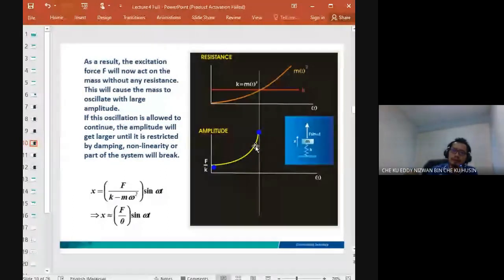When the operating speed is close to the natural frequency, you still can get a high amplitude. For example, if the natural frequency is 10 hertz, the proposed operational speed should be less than 8 or greater than 12. That's the common practice.